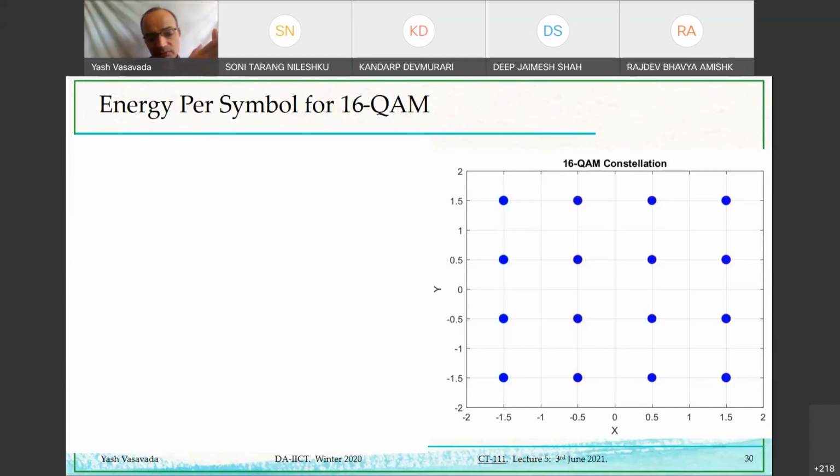So you can reduce the symbol energy, but then because of that, if you end up getting a higher symbol error rate, then maybe you haven't done the smartest thing that you could have done. And so what we are going to now focus on is defining the constellation symbol energy in an average sense. But then we will also want to tie it with the distance that we are introducing between two consecutive symbols. That distance is going to give us a control over the performance at the receiver.